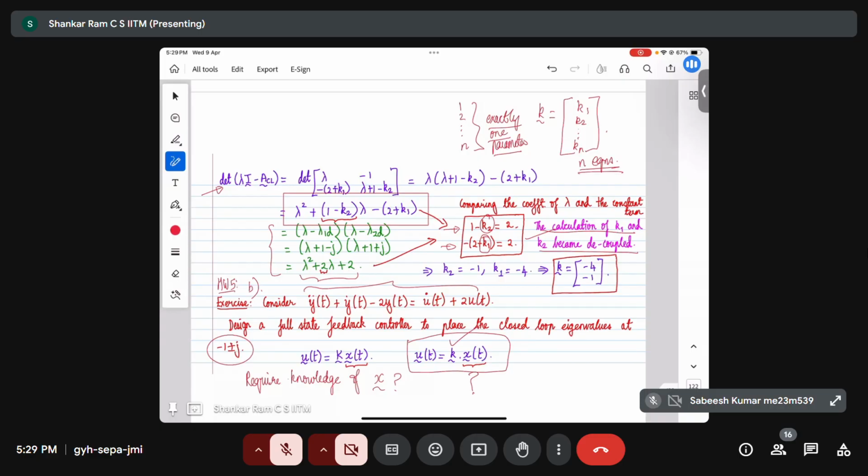Even in the mass spring damper system, let's say X is displacement and velocity. So we need measurements of displacement and velocity to even implement this full state feedback controller. Imagine the order of the system keeping on increasing. Even when you do the heading angle project, you will need lateral displacement, yaw angle and so on. So the question becomes, who will give us all that data?